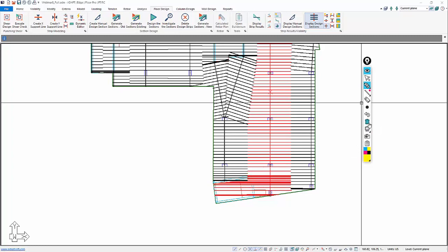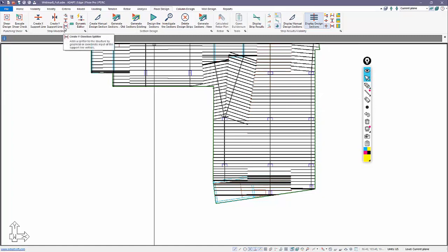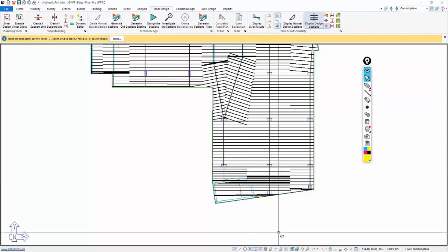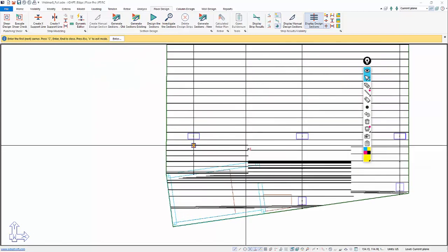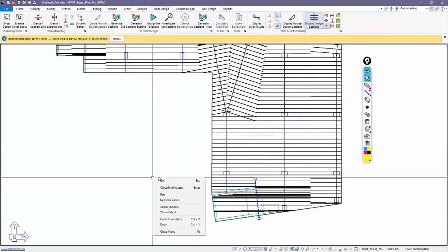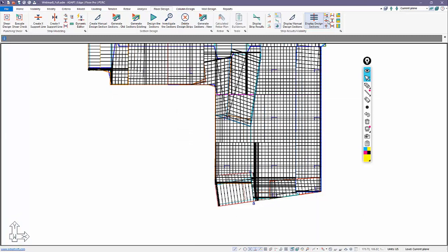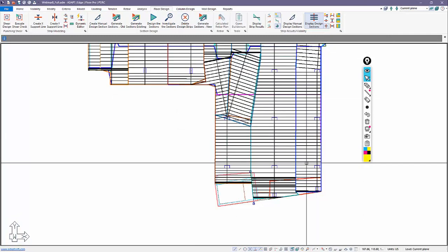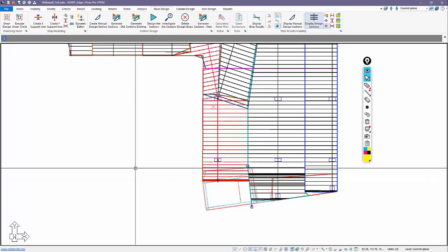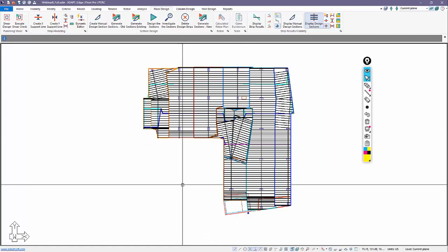splitter. And again, similar to what we did for the X direction, I'll use a Y direction splitter, and I'll just say that this tributary really just needs to stop, let's say from here down to there. And when I do that and I regenerate the strips, we can go back and look at that. This tributary stops, as does this one. Okay, so those are some nice new features with generation of strips.